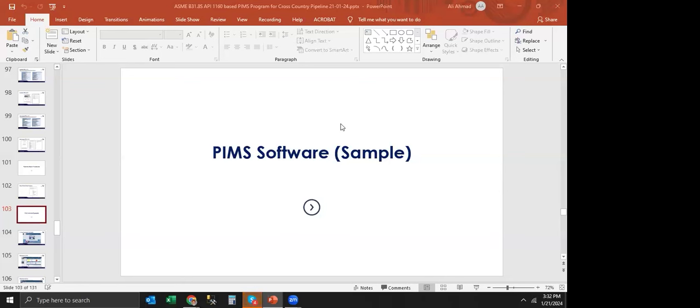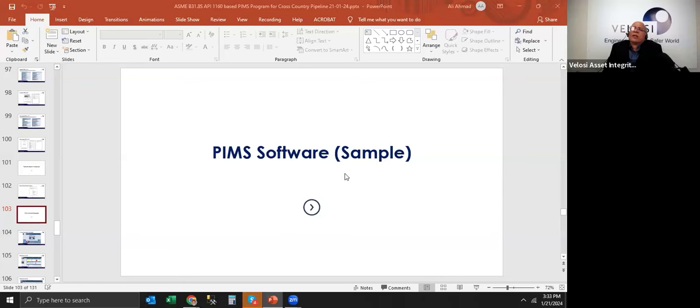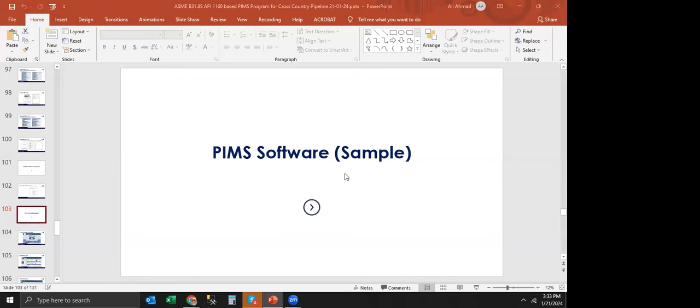So, my question again is, how can we apply ASME B31.8S in a distribution network when it is within the city? We cannot move the houses or the residents if there's a chance of a pipeline burst or something. Then how? Sir, here, 80% of the network is PE, not ferrous material.